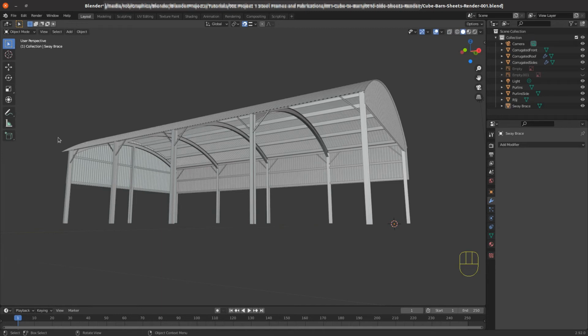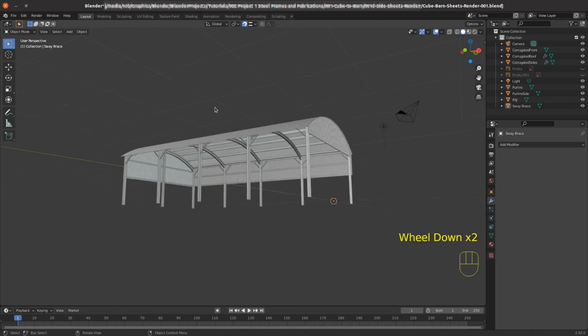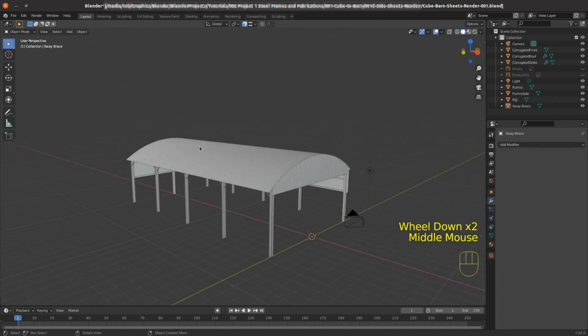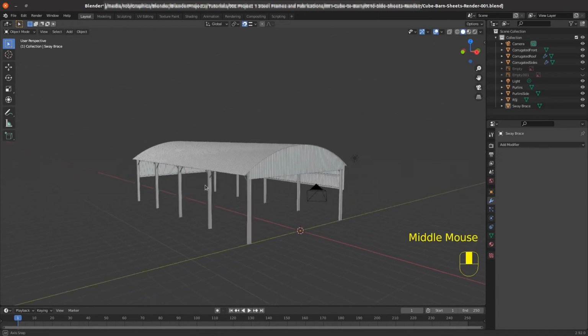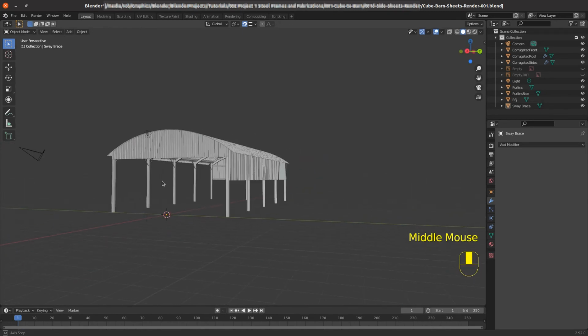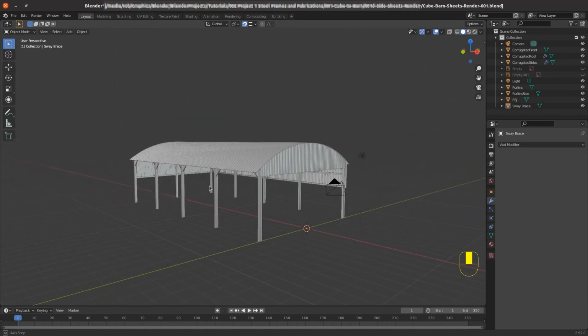If you want to, you can go to far more detail by putting fitch plates to bolt all the sway braces in, plates for bolting the arc of the roof and the back RSJ, brackets that would hold purlins and make them individual. But for a representation rather than an engineering drawing, this gives us a good model of a barn we can use.